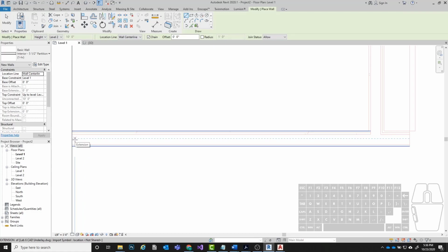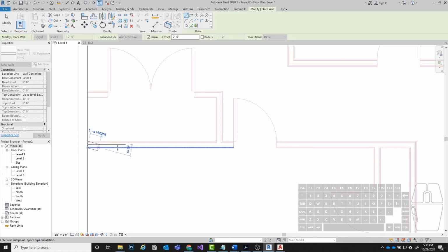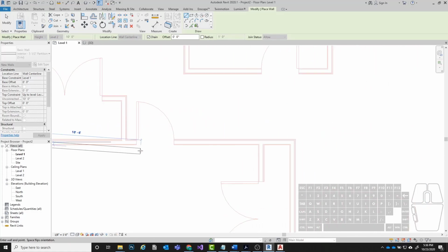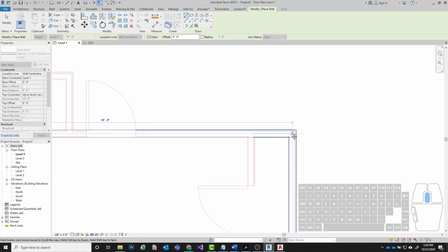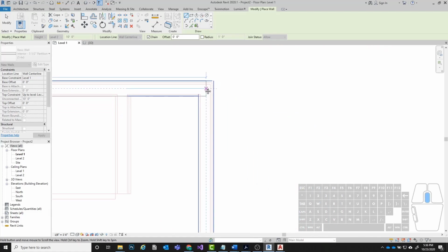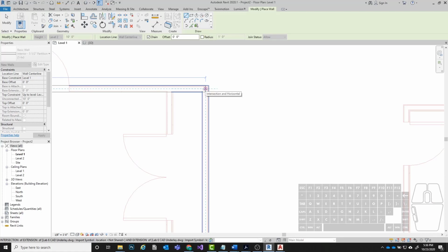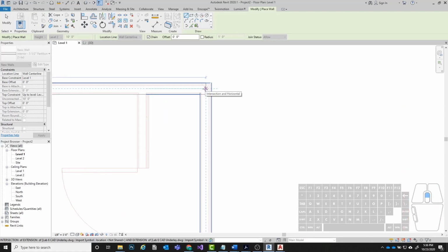These two outermost layers are blue. Then I just want to click on this point here where it intersects with the exterior wall, and I can click and I can drag and I can start drawing. So as I said with the windows, same thing as with the doors. You want to draw all the way through the door openings, and you want to draw until you get to here where your next segment of wall is being inferred with the blue dashed lines.